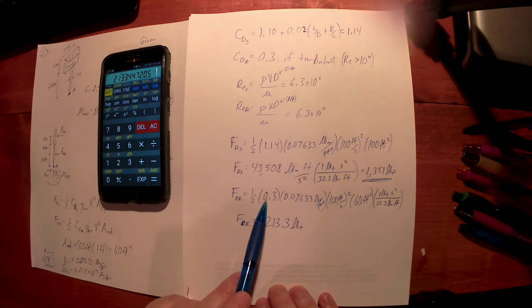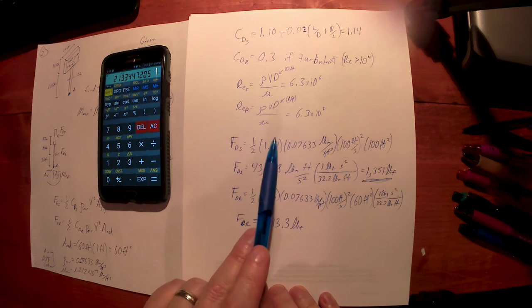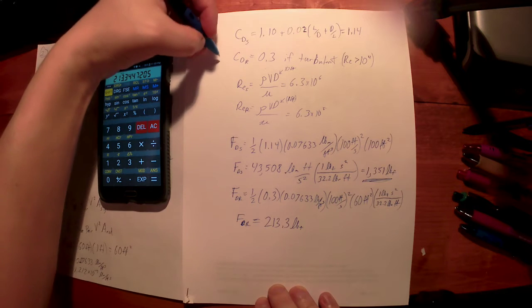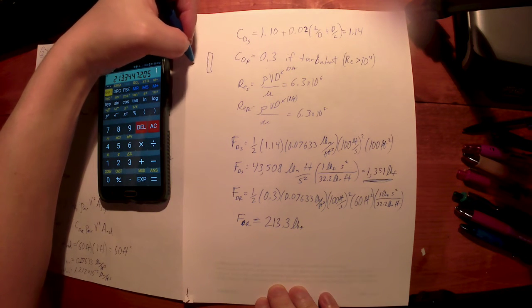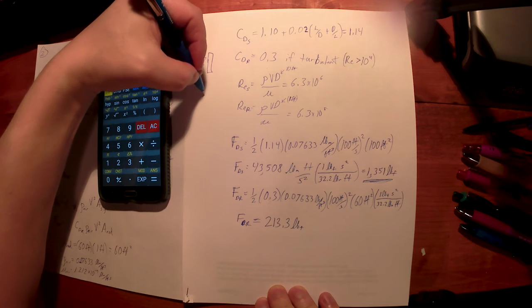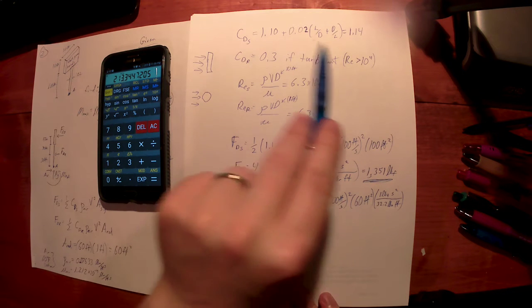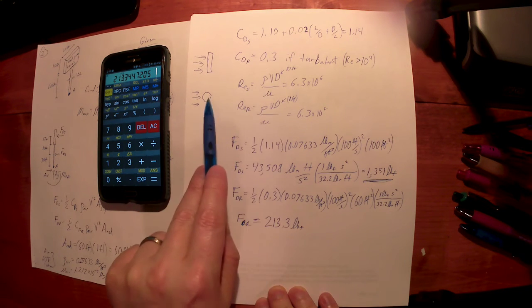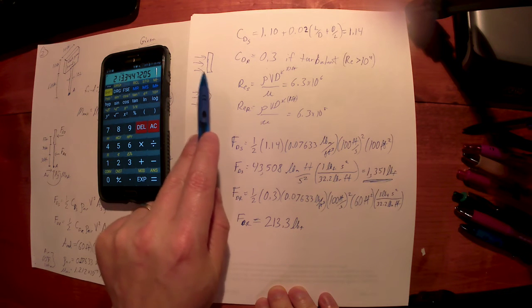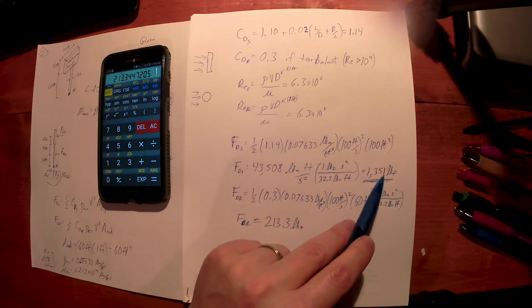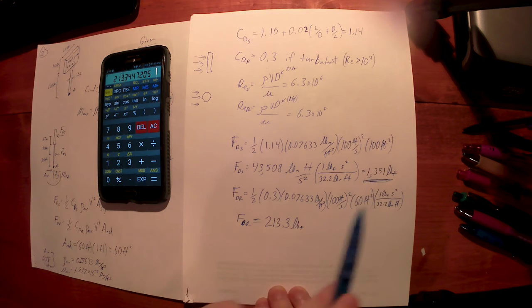Again, why is it so much less? Well, look at your drag coefficient. A big square profile, bigger drag coefficient. A smooth, rounded surface, the air is able to move over that surface, right? If I've got air trying to get past this, as opposed to trying to get past this, you see why the drag coefficient is so much bigger for this one than it is for this one. It's easier for that air to flow around it. Can't really flow around this nearly as easy, so a bigger drag coefficient on the sign, so a bigger force. Not a whole lot of difference in the area, but a bigger drag coefficient means bigger drag force.